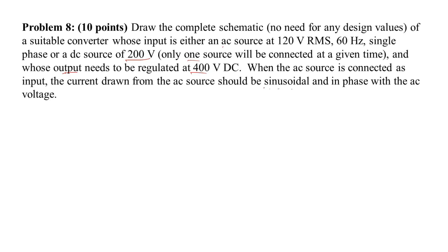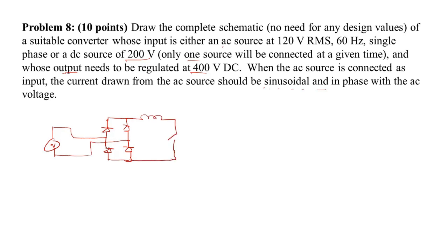So that immediately suggests that you need a PFC. So let's draw the PFC first. For the AC input, this will be your power converter. Just a standard boost PFC, because we need unity power factor operation. The AC source gets connected to the diode bridge. Output of that goes to the boost converter. And you can put a load as well.